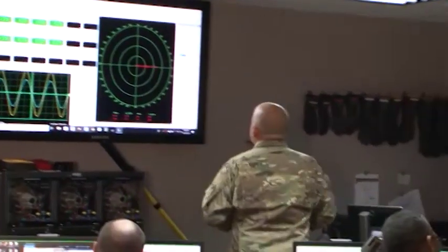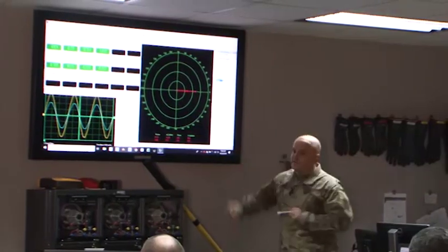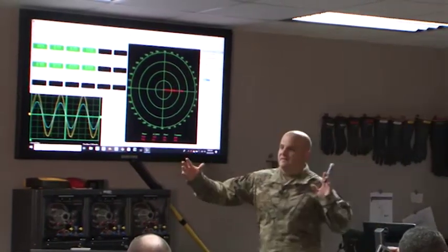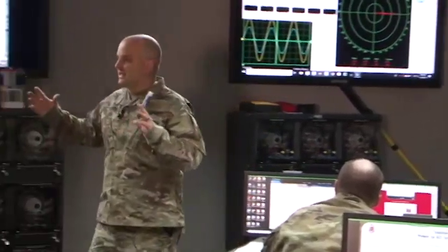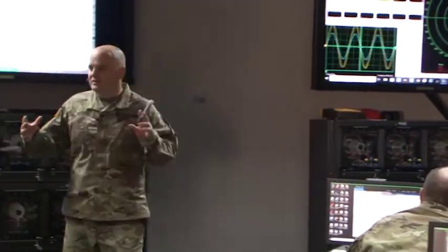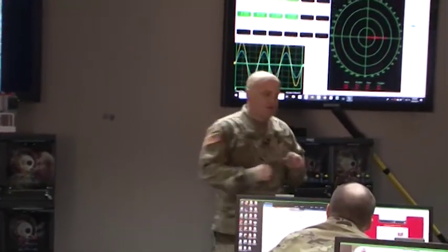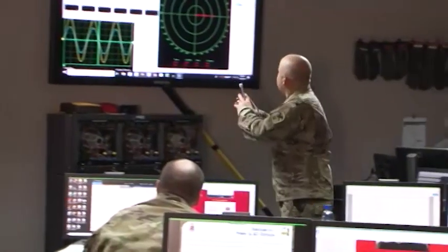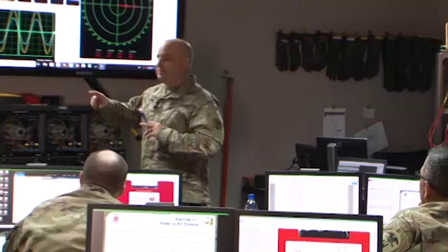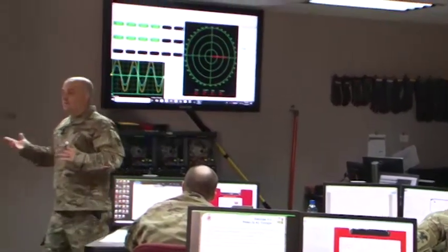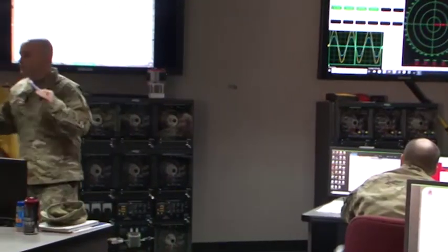Okay, so we've got this. We see no phase angle difference here, correct? Now we look at our phasor diagram. Now the length of that phasor, that vector, is what? What does the length indicate? The value. Directly correlates to the value, right? To the peak of that sine wave, right? To the magnitude of the sine wave. And right now we're seeing that the current vector is laid completely on top of the voltage vector, right? And that is because why? They're in phase. There's no angular difference between the current and the voltage, correct?